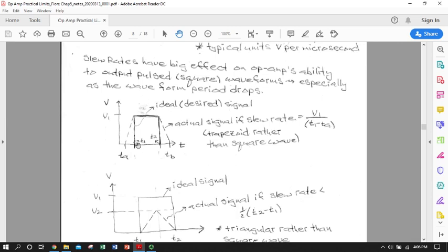If we imagine this, it is obviously a dV/dt of infinity. If we defined another T here, TA, which of course wouldn't be applicable in a real circuit because it wouldn't start responding until we got to T1, but we could define a TA and say the difference between T1 and TA would be the delta t that you divide V1 by, and this dashed line would represent the effect of a slew rate maximum.